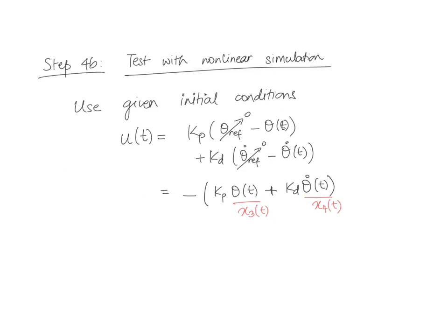With the nonlinear simulation, you need to check whether this control system designed with the linear form works. You designed it for a simpler model. That's why we need to do this check, and this is not just a sanity check, this is actually a fundamental check. We don't know if the control we designed is actually going to work on the nonlinear model, so that's what you need to identify. If it doesn't work, or maybe it works kind of, but it doesn't give you the performance, your job is to then tweak these gains, Kp and Kd, such that you get slightly better results.